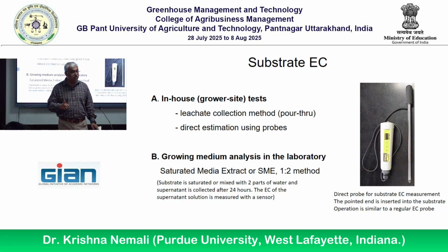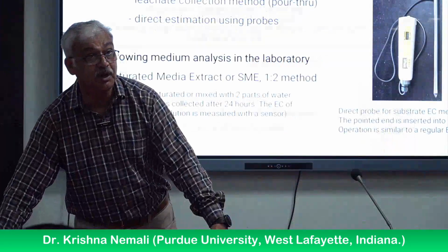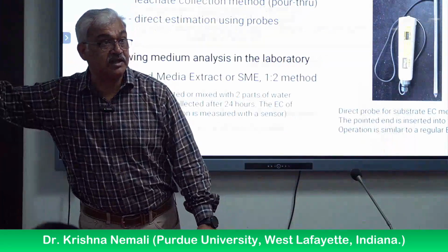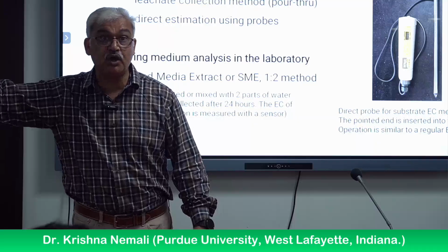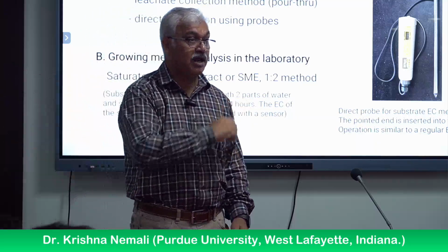So that's bulk measurement. The pore water measurement, or pore water conductivity, I'm going to explain in the next slide. But keep in mind, there are two types of EC measurements. One is measuring the fertilizer solution you are supplying to plants. That's in the tank, and it has nothing to do with the soil or substrate. You are mixing it every day and sending it to plants.